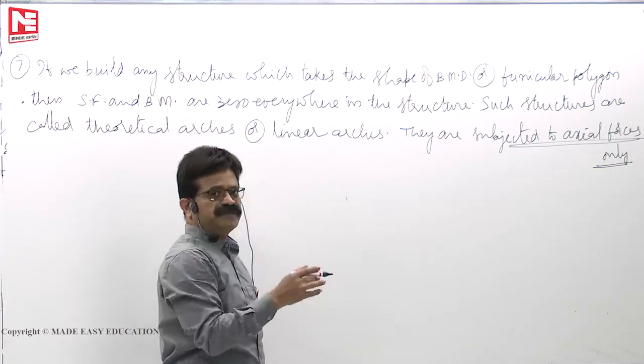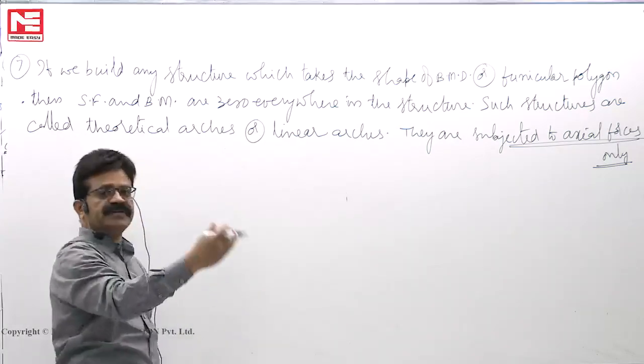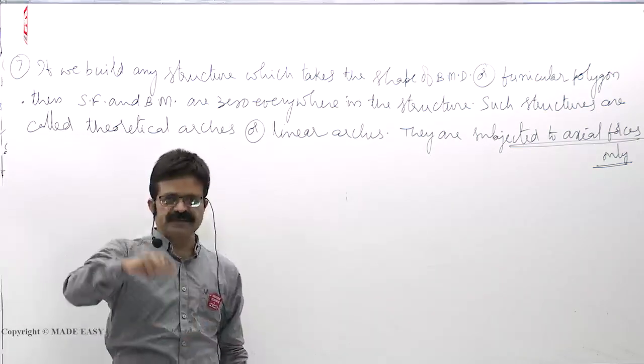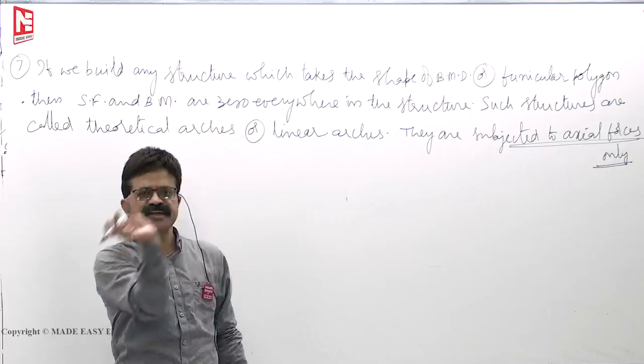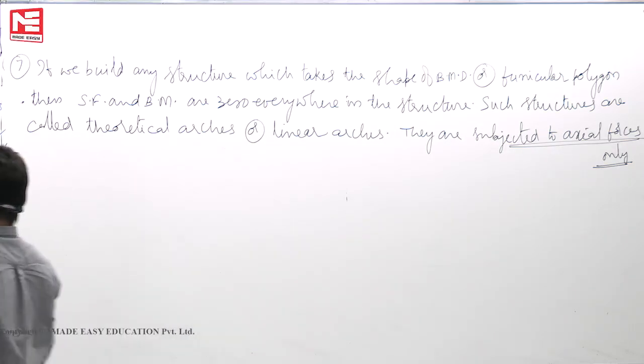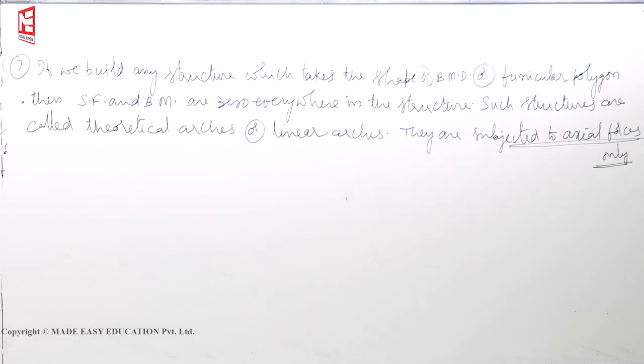That axial force can be compression or tension depending on whether it is below the reference or above reference line. Below reference line means tension will be there, above reference line means segments are under compression. Okay. Now, let us see the 8th point.